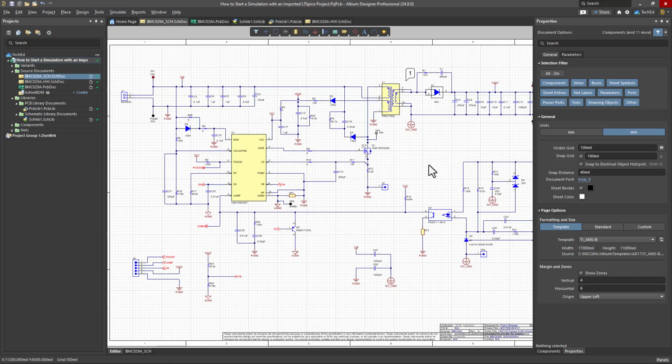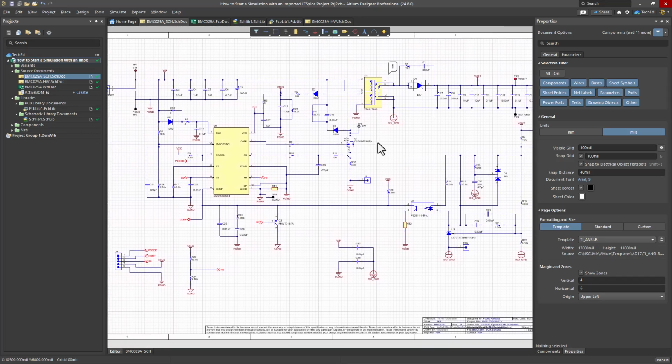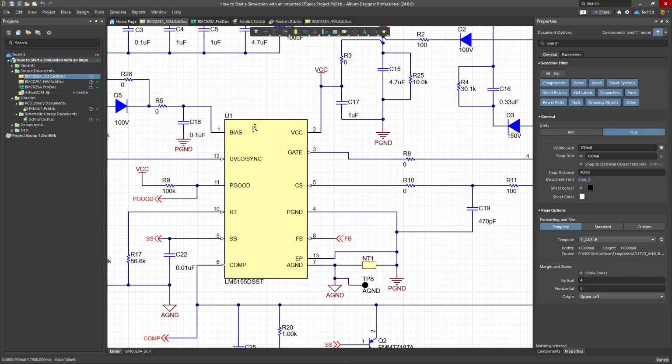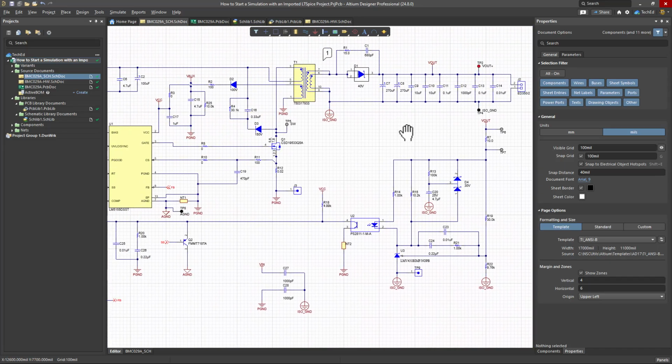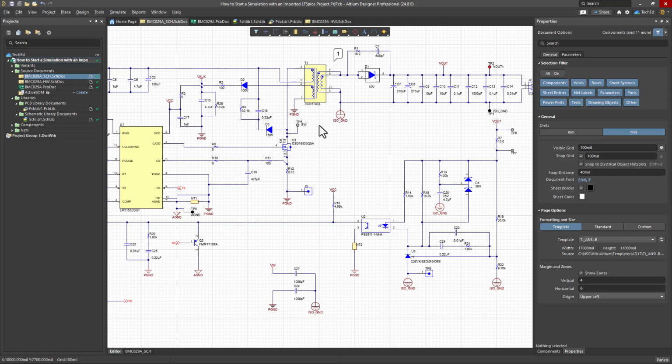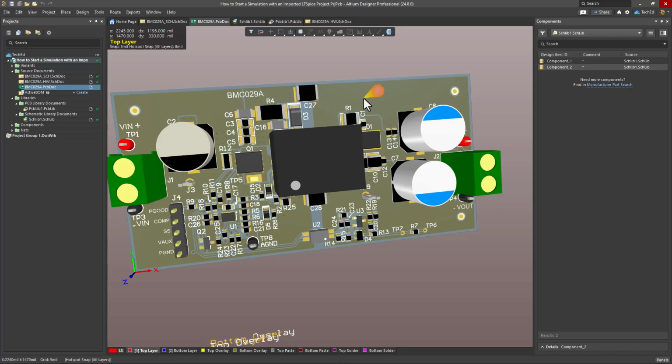The schematic in the PCB design process, if you're new to it, captures all of the conceptual, high-level component symbols. These are just drawings or symbols to represent real devices in real life. You wire them up, and this is the overall plan for how to get a functional design. The electronics design engineer will send the plan to the PCB layout expert, who's an expert in mechanical design, signal integrity, and EMI, and tell them what to watch out for electrically. These two jobs are still separate, but more and more electrical engineers are being expected to know how to do schematic and PCB layout as standard.